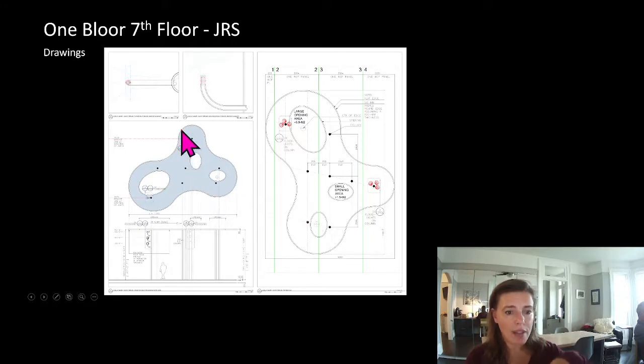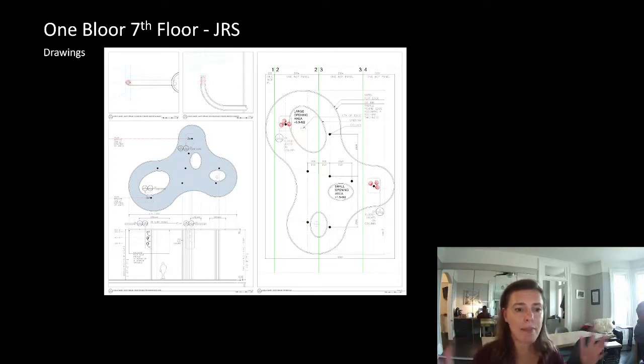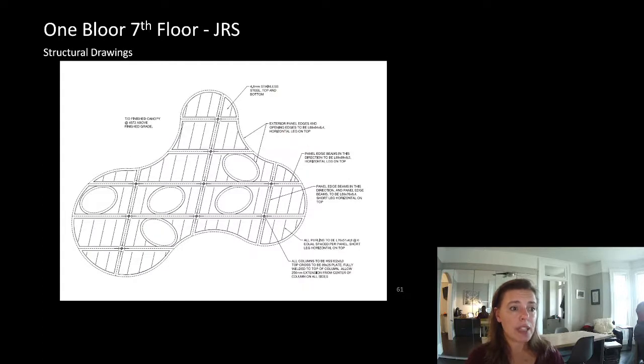So yes, we have gravity load and uplift, but the bigger one is our lateral loads. We're not connecting back to a big, robust building. We have this stacked on spindly little columns. What they did is they built steel angle frames in sections that came to the site and were fastened together, then had the shiny plate steel put on and buffed to a very, very high gloss.